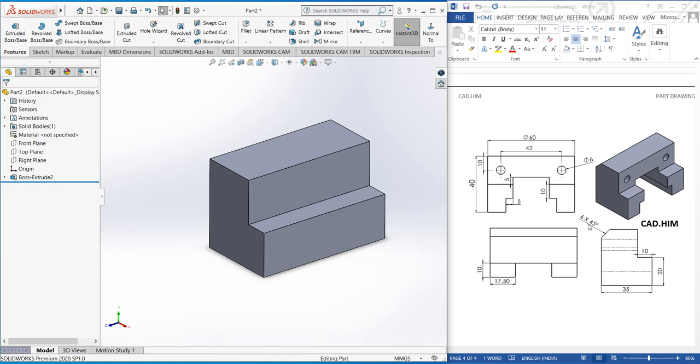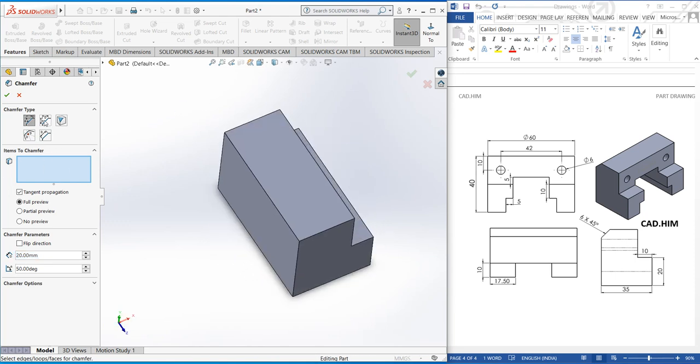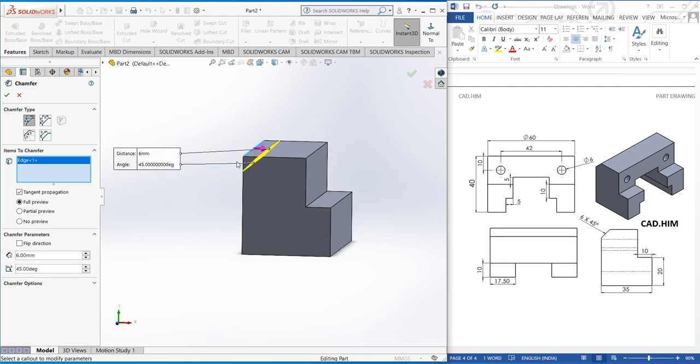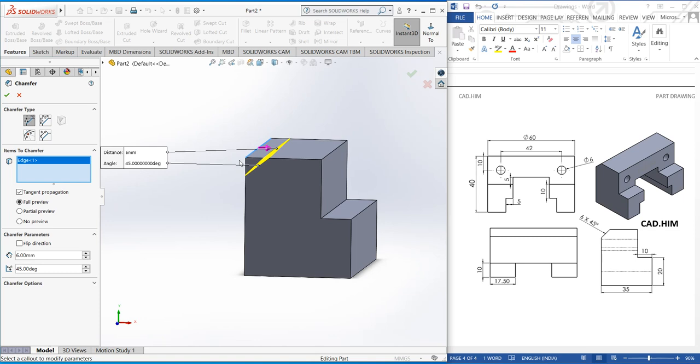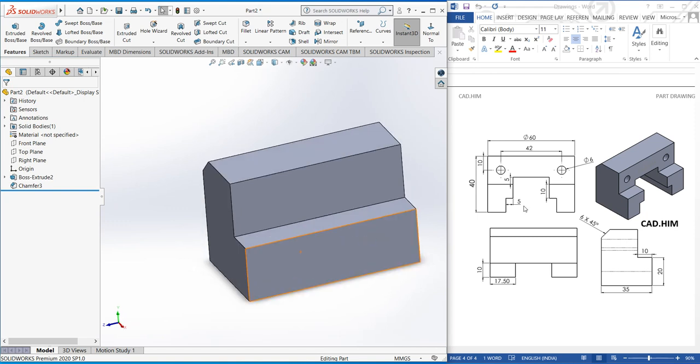So we have this chamfer 6 into 45. So we go for this feature, fillet and item to chamfer, and we have this angle and distance, right? So we click here. Angle distance is 6. Angle is 45. Means both sides are equal. We can also use distance and give the symmetrical option of 6 mm. Okay. Let's just click OK. So it will look like this. Now you can see in this face we have this structure, this one,